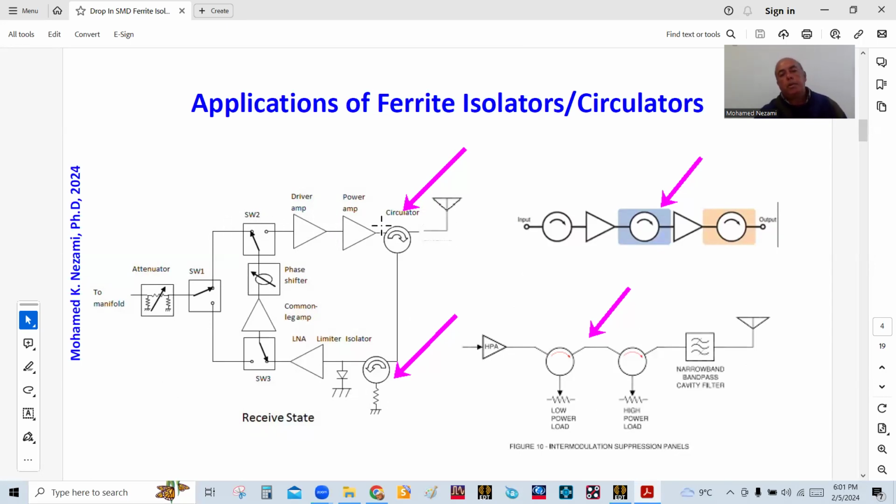So on the transmitter, you can transmit and then use a circulator between the antenna and the power amplifier. First of all, to protect the power amplifier and to isolate the receive path. So when you transmit this way, nothing will come back this way, or very little. Or if there is some that leaks into here, it goes in here, and again, it gets absorbed in here.